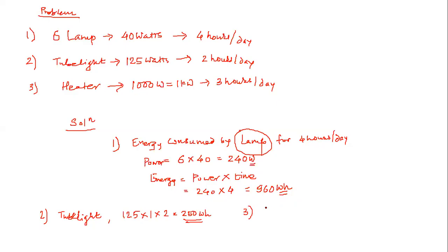heater, right? Only one heater is there. So 1000 into one heater, and it operates for 3 hours, right? So this will be 3000 watt hours. Now what will be the total energy consumption in a given day? I need to add all this.